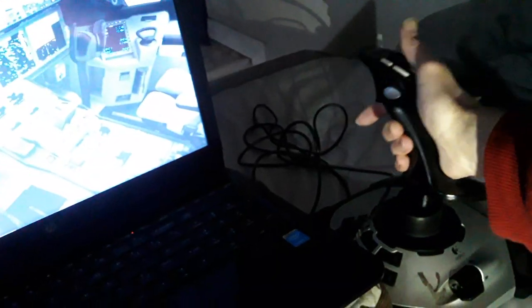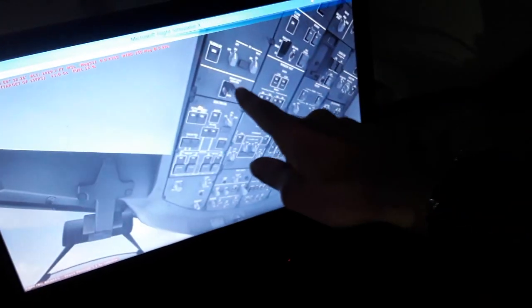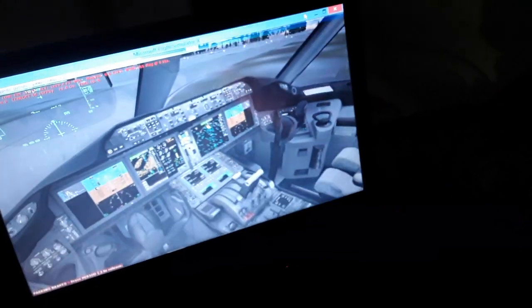So when we make a side stick deflection in the Airbus or the yoke in the Boeing 787 or the 777, we give a command to the flight control computers, depending on the mode the flight control computers are in. So we have the normal, the alternate, and the direct mode of the flight control computers, like in the Airbus. Also the direct and the mechanical backup.